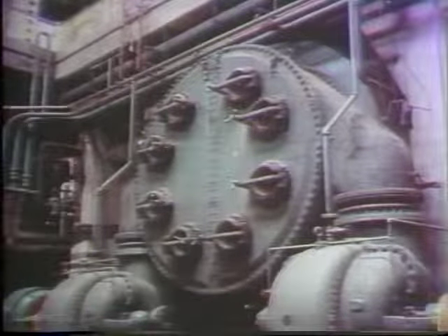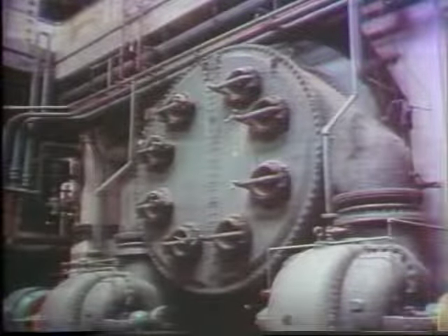Scrubbers and other external anti-pollution equipment do very little to reduce the amount of nitrogen oxide released by a boiler. Instead, we control their formation by controlling furnace temperature. A number of methods are employed to reduce the temperature of furnaces. Adjusting the fuel-air ratio will slow down combustion, and recirculating flue gas back through the furnace will accomplish the same thing. You'll need to find out what methods are used in your plant to reduce the amount of nitrogen oxides released into the atmosphere.